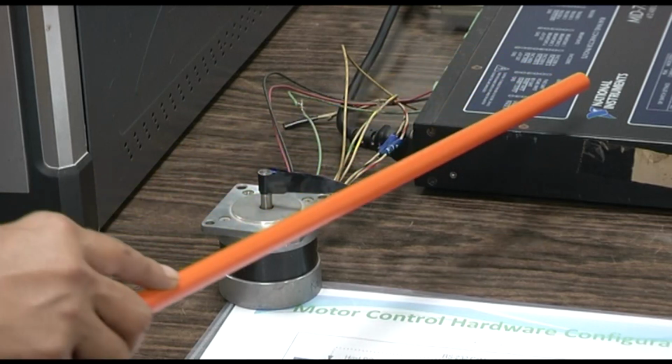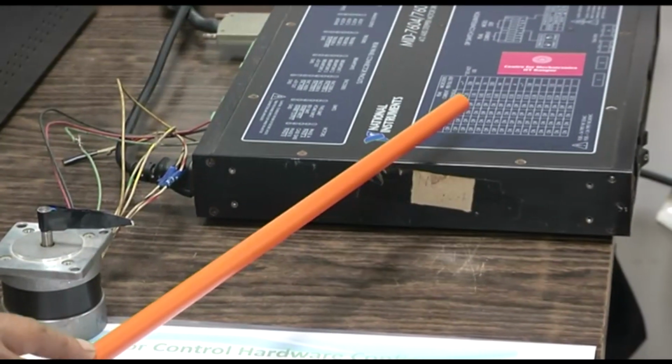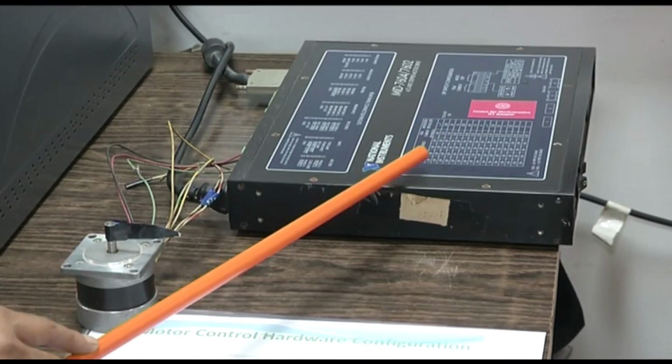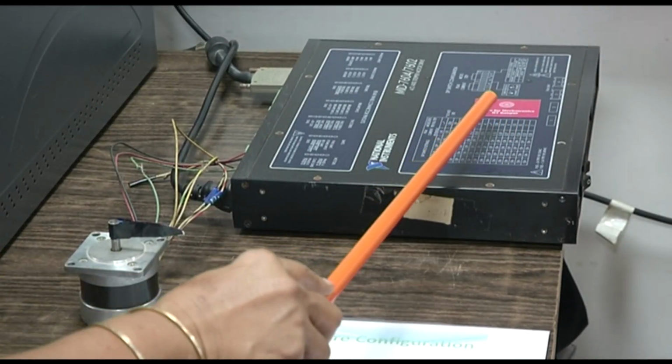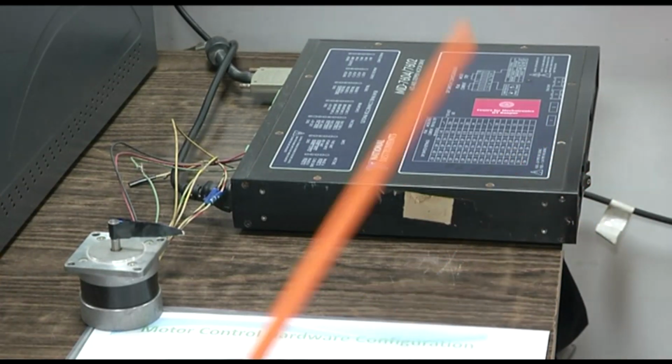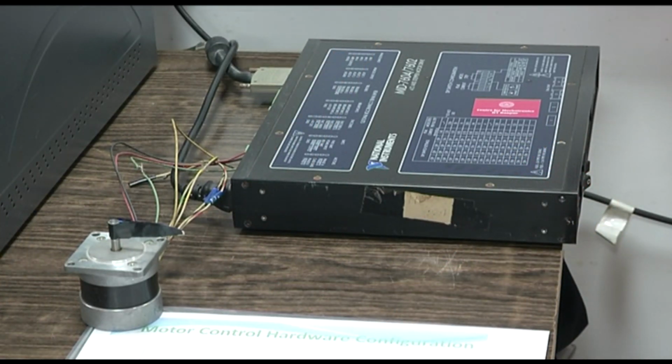Because there is a provision of gearings. Having soft gear, we can set these values by selecting the dip switches here. So, that is the beauty of using dedicated hardware for the purpose, like the motion drives which we are using here. For changing the direction we need to give a minus as the position here. So, now you will see the motor is reversed through one rotation.